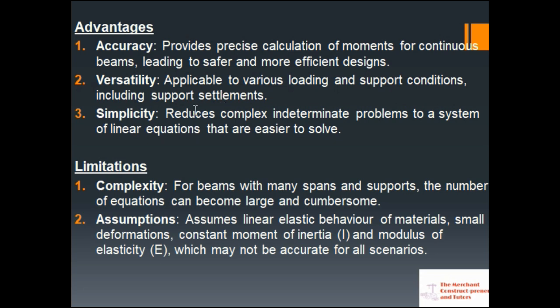This is another aspect of it. It is versatile. No matter the loading condition, no matter the supports, you can use the three-moment equation. Simplicity: it reduces complex indeterminate problems to a system of linear equations that are easier to solve. Once you break it down to just linear equations, you are good to go. So the limitation now is complexity. Depending on the number of supports, when you have a complex number of supports, then there's a problem.